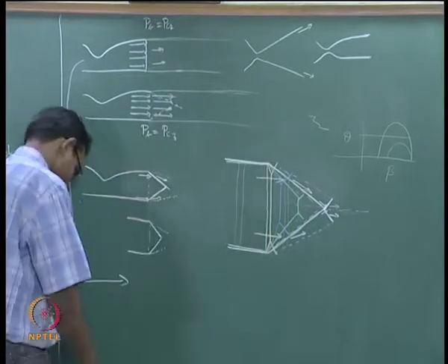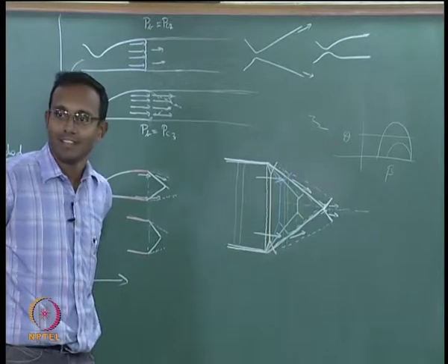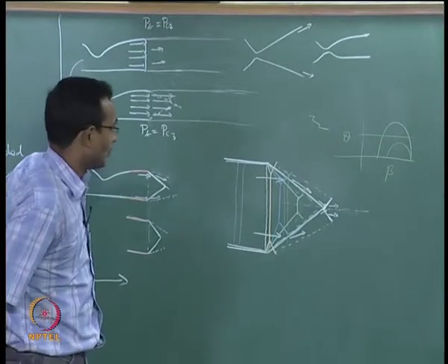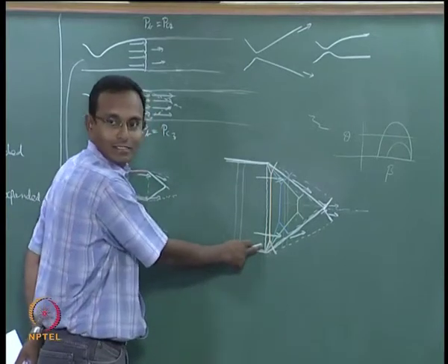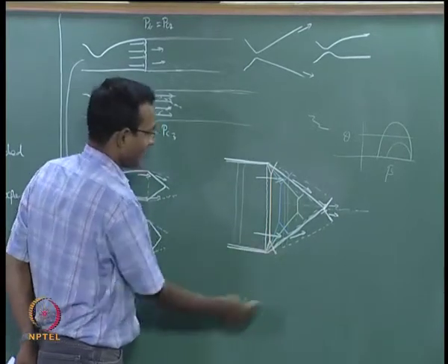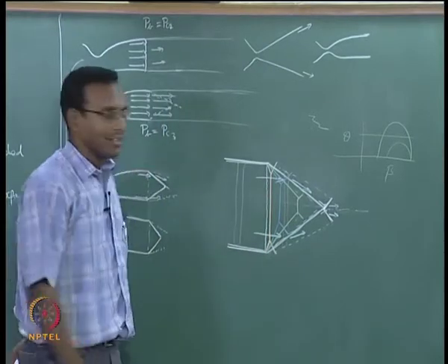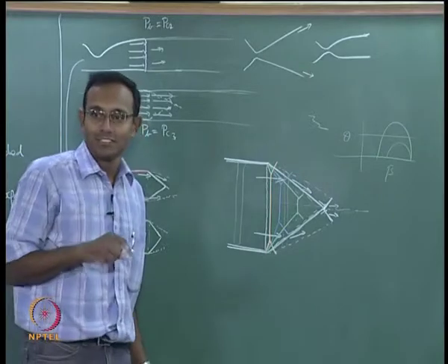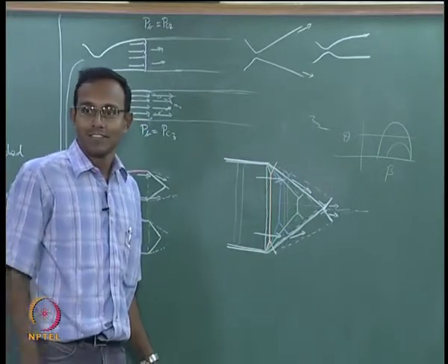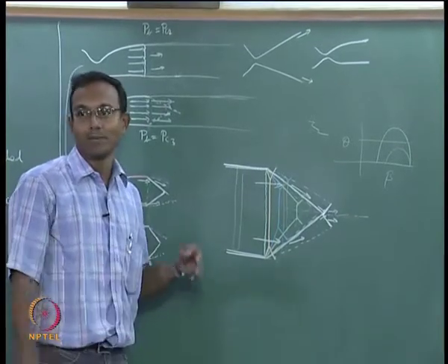So, if you look at it, shock is doing a continuous change. Okay. If I think about PC2, my shock is sitting on the exit like this, white. If I decrease it slightly, it is almost normal shock most of the places, only some portions it is oblique shock, which means only those regions the pressure is lesser, other regions it is roughly the same as this original exit pressure.